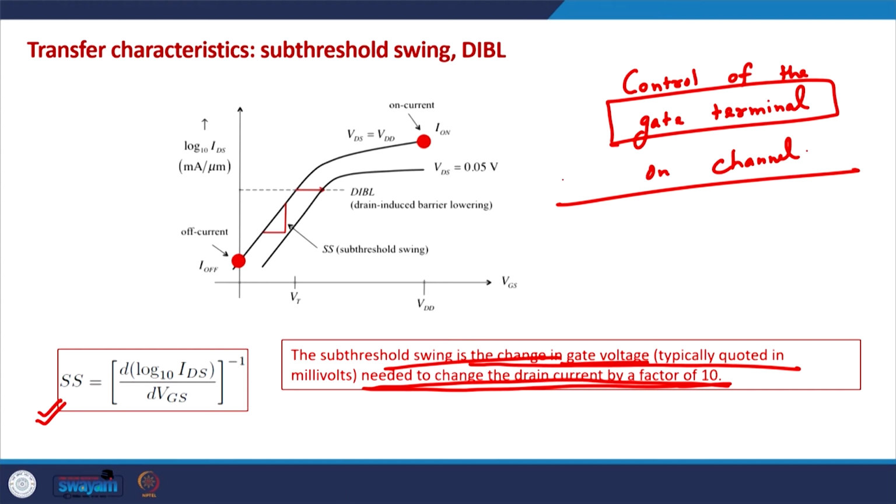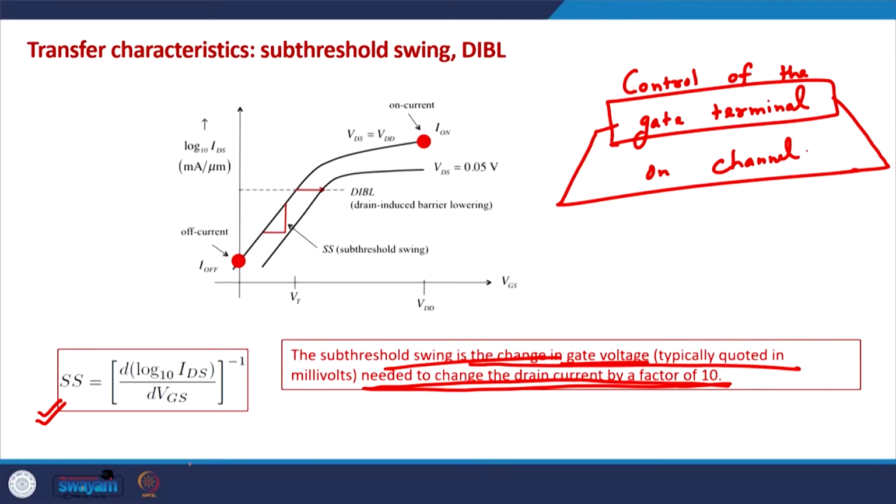Since, as all of us know, ideally the gate terminal is the control terminal, it is generally better to have the sub-threshold swing as small as possible, which means we want the control of the gate terminal to be as large as possible. So, we would always like to minimize the sub-threshold swing parameter in MOSFETs, and there is a fundamental limit up to which this can be minimized.